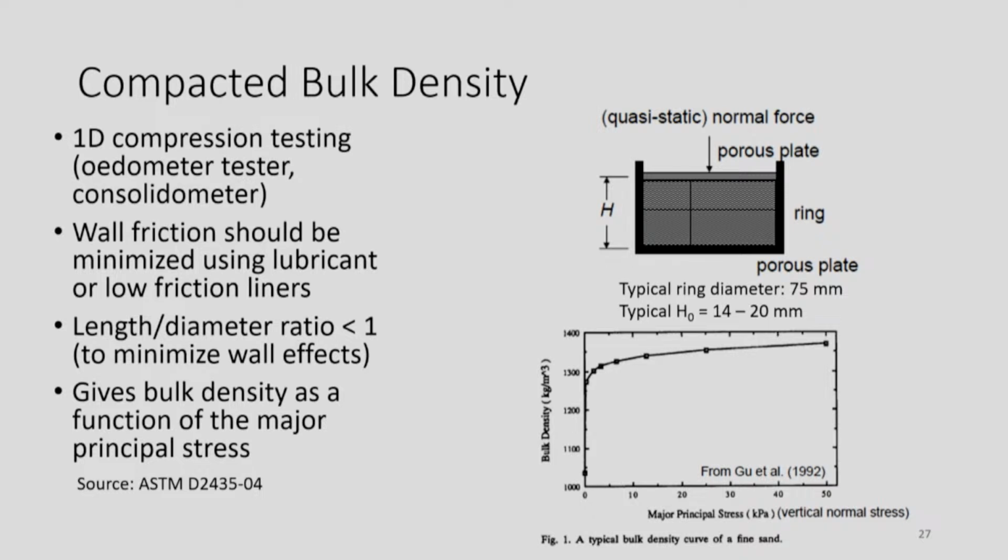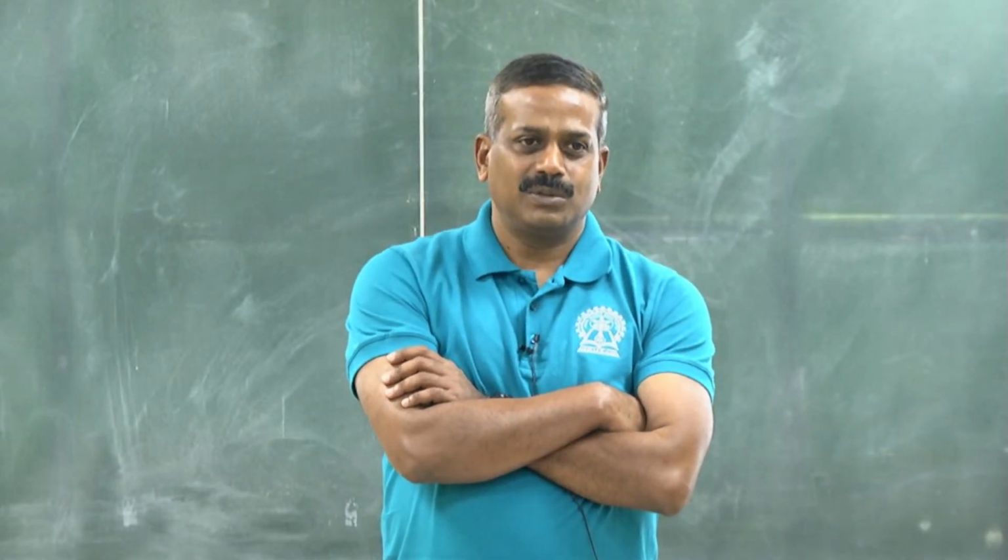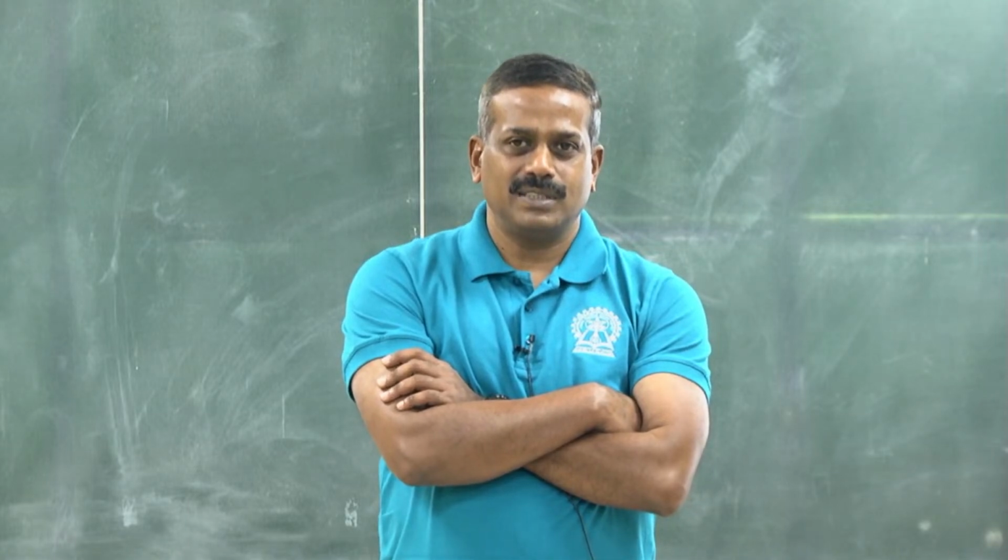You all would have learned about pressure, right? Compaction pressure, calculation of pressure in bins and silos. You remember the equation name? What's that? Those are for stresses, right? For calculating pressure at different heights. Yeah, Janssen's equation, right? So that's very commonly used, right?